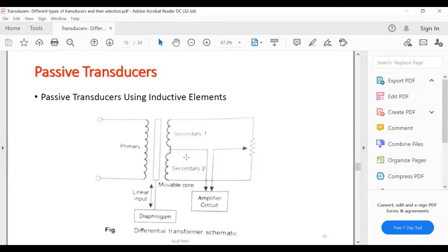The magnitude of the output voltage changes with the amount of displacement of the core from its central, neutral position, and its phase with respect to the voltage at the primary winding depends on the direction of the displacement. The nonlinearities in the magnitude of the voltages induced in the two output coils compensate each other, and the output voltage of the differential transducer is proportional to the core movement.